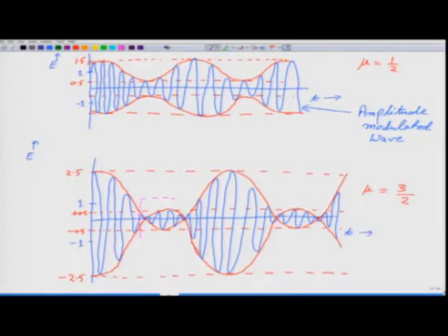Let us have a look at the graph. So this section is unwanted. Similarly, this section is unwanted, because at the receiver end, although this signal was not present in the original message, it has now appeared in the amplitude modulated wave, and this will distort our signal. So for efficient communication using amplitude modulation, the value of mu should not be larger than 1.